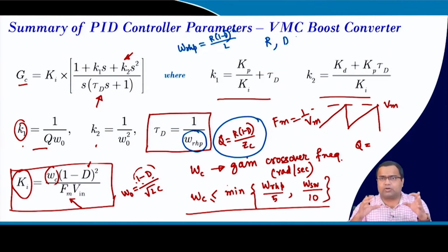So, if we design by the traditional way, where we design this compensator, the PID controller or type 3 compensator, at the very beginning stage using off-the-chip components, and then we leave it, then throughout the process, when there is a load variation or supply variation, we are not going to change it in traditional analog control.